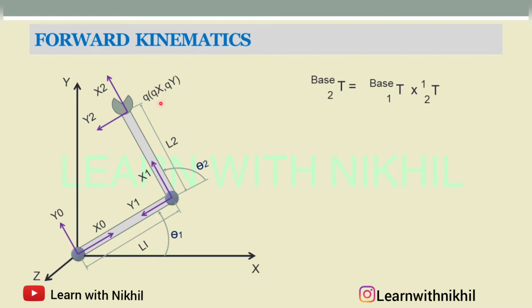That is joint 2, which is the end effector, which is equal to the transformation of joint 1 with respect to the base, multiplied by the transformation of 2 with respect to the previous, that is 1.